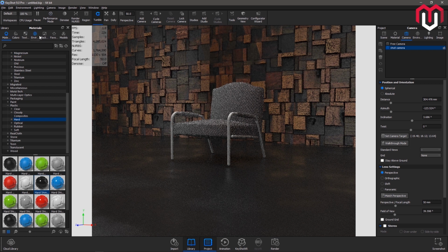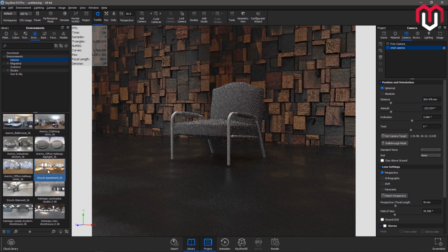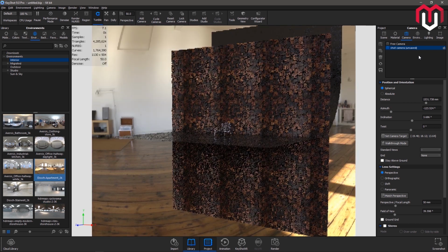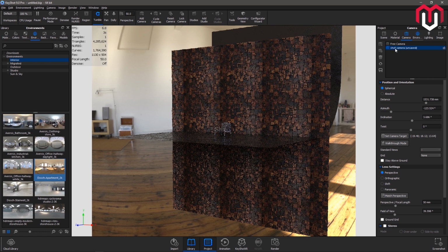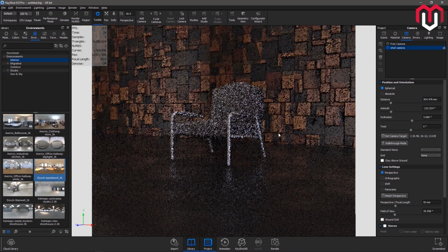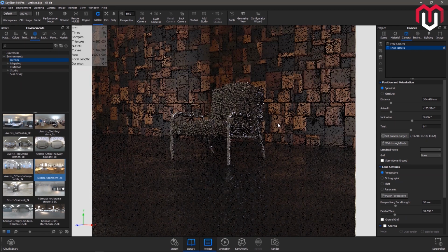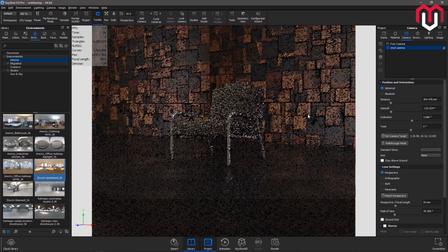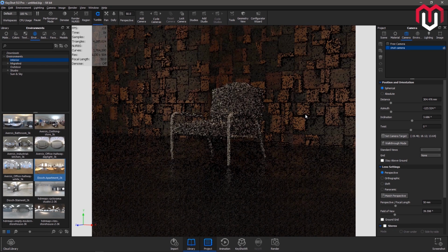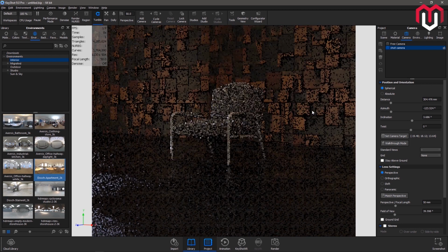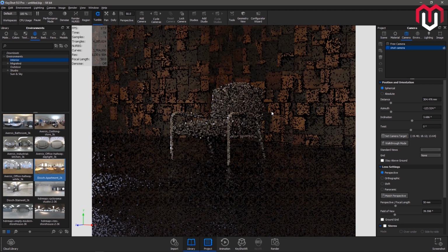With the material stuff done, the next thing is the environment. I have applied this one for the zoom out here for the outside. So let's go to our camera again, click on this one, and you can press Ctrl and drag. That will let you change the lighting settings. And wait. Okay, it's too dark. Keep doing it until you find what you like.